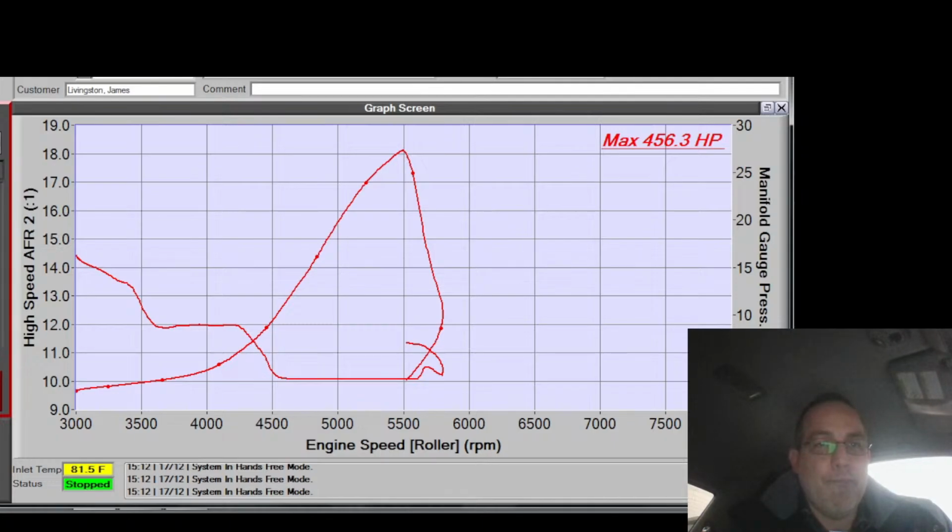Okay. Yeah, I'm just not seeing anything. Let's compare this to stock. See what other wall wetting tables I changed since stock. Just that one. Okay, so there's only that one that I adjusted, so I can change more. I just don't like to change them a bunch because the engine isn't that different.